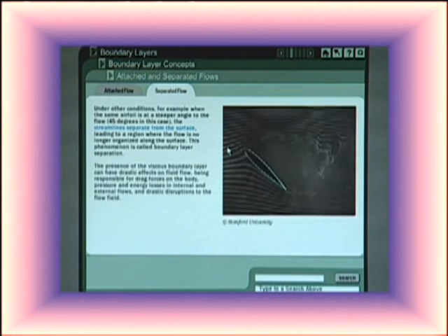In this one we have a flow in x direction, and this aerofoil is kept in a different manner. Now, in this video we can visualize that from this portion to this portion the fluid is separated. So, on the downstream side of this aerofoil we have a wake where the fluid is said to be separated, but on this surface the fluid is in contact with the solid boundary, and here also, and here also the fluid is in contact with the solid boundary. Only on this back side it is getting separated, right.